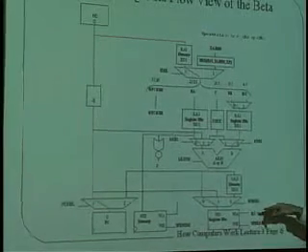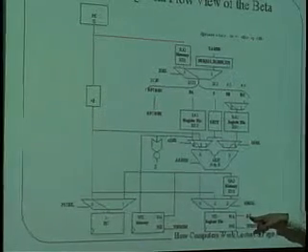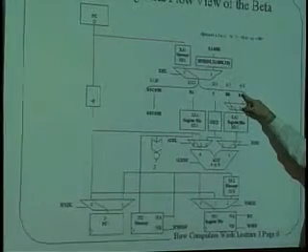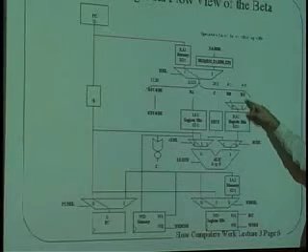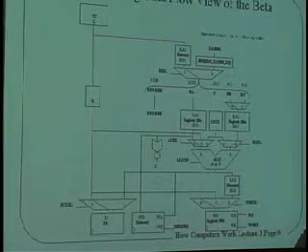And then the write address, where is that going to come from? Well, that's going to come from RC, which actually is a nickname for this thing up here, because register C is the number of the register that we want to write the data into. And that's going to come down here, and it's going to tell us the address that we want to write the data to right there.